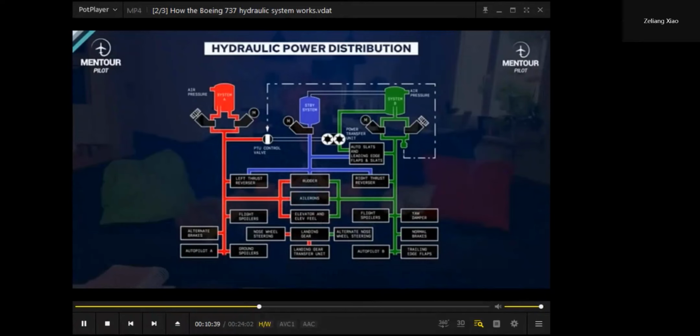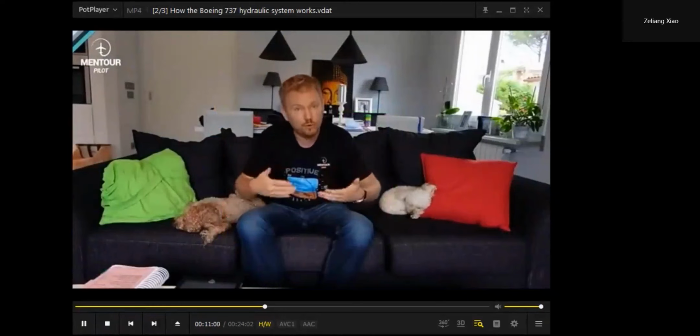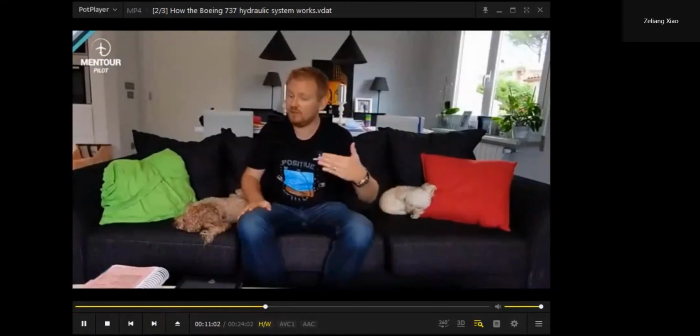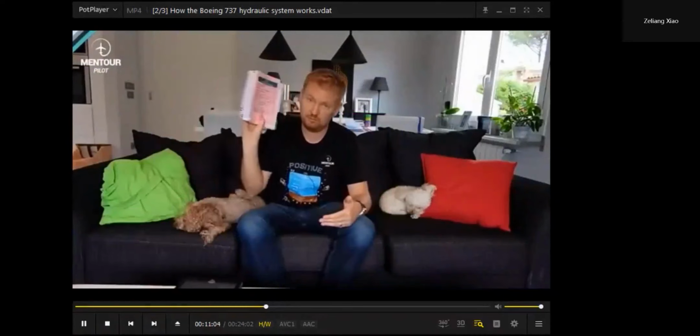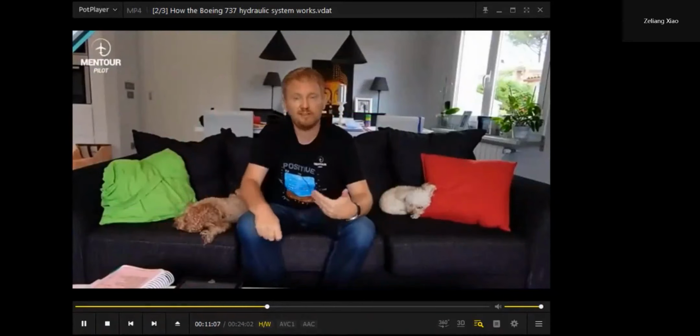Now, as you can see from the schematics here, there is no other connection to the landing gear extension or retraction, which means that if you lose system A for whatever reason, well, then you need to have a separate standby system to extend the gear. And we do. We use the alternate extension system, which essentially is just using gravity to let the gear fall out by themselves. There is a specific checklist for that, and it entails basically just opening the up locks.